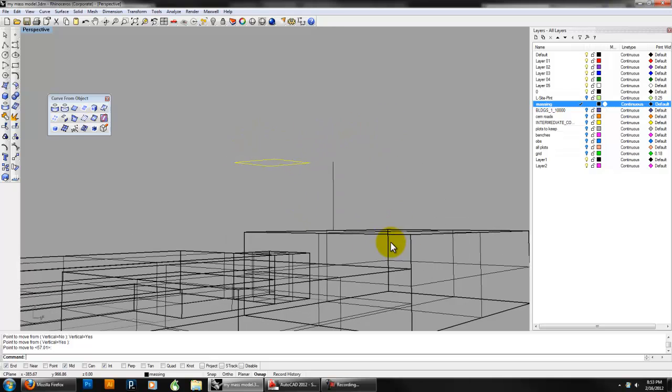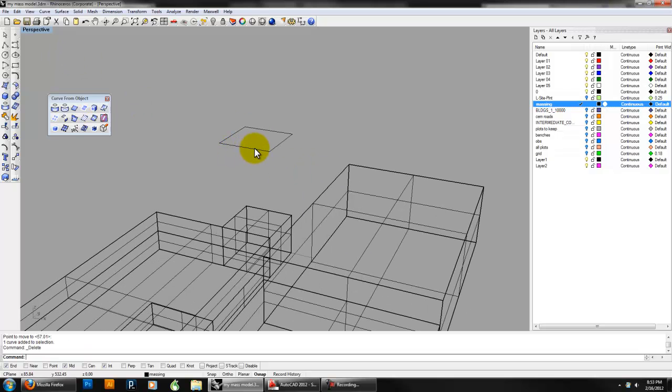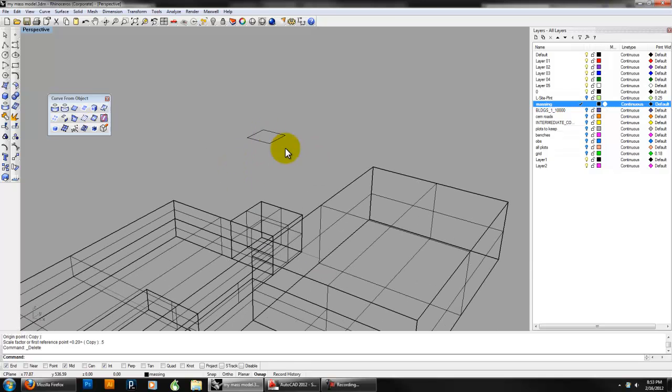If you know what this is, you could just move it to that height, but I did it visually. And then I'm going to draw a line across this, draw midpoint snaps, and I'm going to scale this object to be half that size, so 0.5. Okay, so I have a curve that I had from here, and I moved it up and I scaled it.